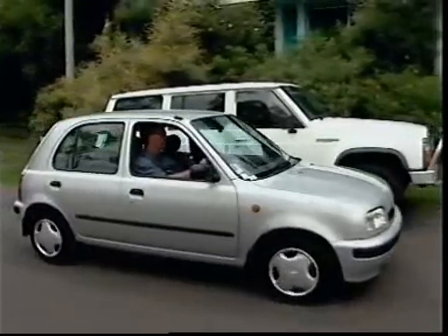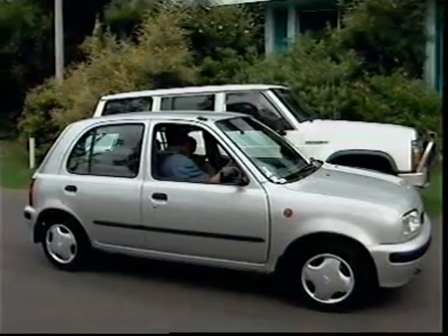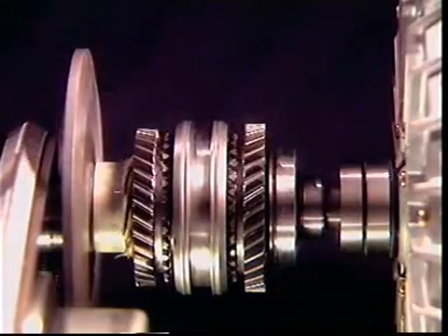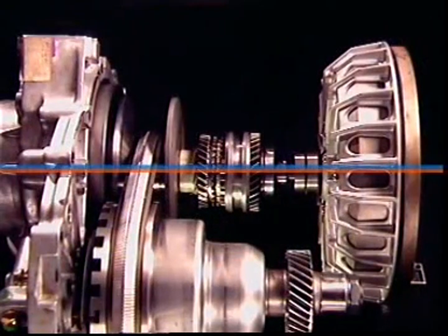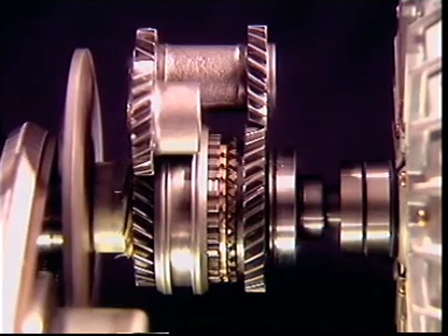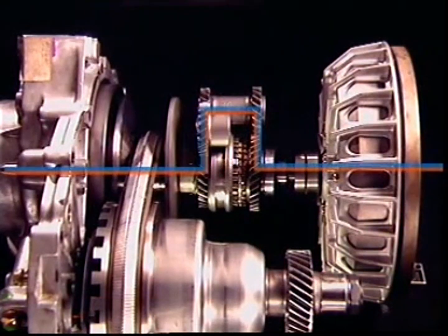Forward or reverse motion of the vehicle is obtained by placing the selector lever in drive or reverse. In drive, a synchronizer assembly connects the magnetic clutch directly to the primary pulley of the variable transmission. In reverse, the drive is transmitted through a reverse idler. It changes the direction of rotation of the primary pulley and the transmission.